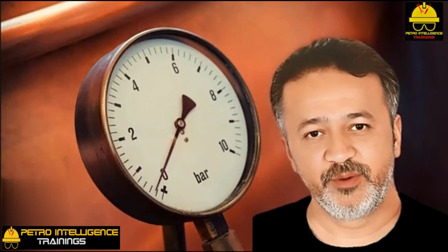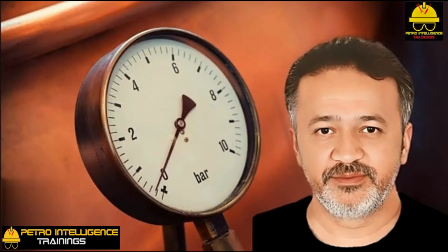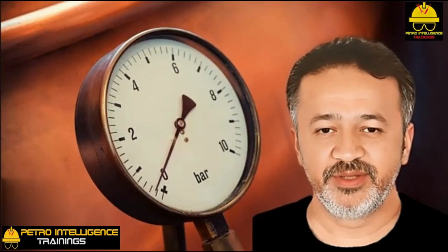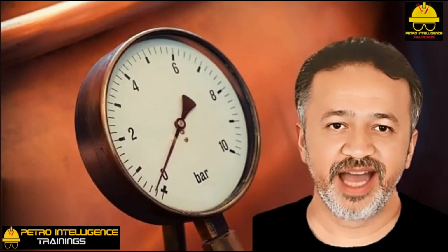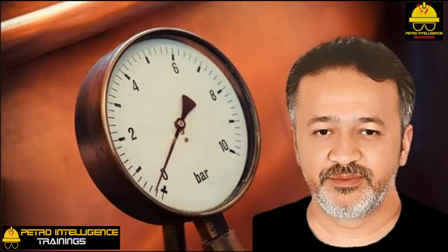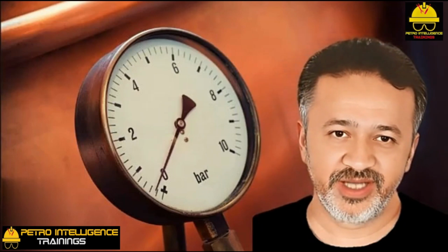An ordinary vacuum pressure gauge or indicator would then read an improved vacuum. But in reality, the vacuum has not changed. The opposite problem would occur in Denver, the mile-high city. At sea level, full vacuum is 30 inches of mercury. But in Denver, full vacuum is about 26 inches of mercury.